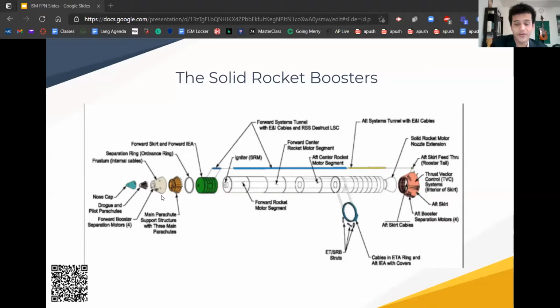One of the most interesting parts of the solid rocket booster for me are the thrust vector controlling systems, which is the TVC, which you can see in the back in kind of this orange color. These are essentially components of the rocket that are integral to the fine-tuning of its trajectory. So it's not just propellant leaving the booster. There are vector controlling systems that fine-tune the trajectory of the solid rocket booster. It allows the rocket to roll in the appropriate direction once it leaves the launch pad and constantly adjust the rocket's path throughout its trajectory. In technical jargon, you could say that the TVC systems have hydraulic gimbal servo actuators, and that's, again, a mouthful to say, but they are just referring to the fact that the motors on the solid rocket booster swivel or gimbal and are powered by fluids, or they're hydraulic. The swiveling is how the attitude and trajectory of the vehicle is fine-tuned in the 3 dimensions called roll, pitch, and yaw.